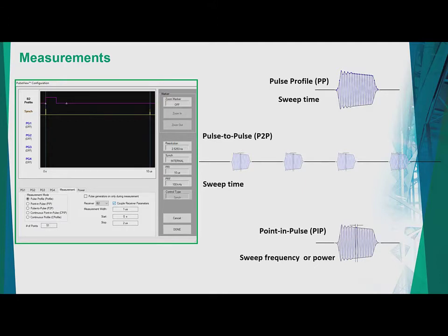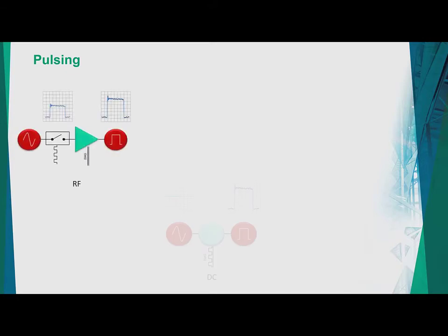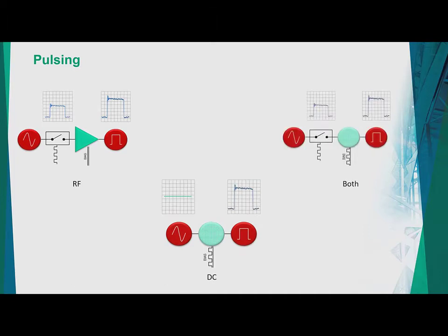We also touched base on why pulse testing is required in various domains. It's a measurement which is more often used by radar applications or people in the radar segment, especially the system integrators, and it's also used for on-wafer applications wherein the DUTs cannot be tested for a longer duration of CW waves, and that's why they need pulsing. The pulsing can be done on two grounds. One is RF pulsing, and the second could be DC/IV pulsing as well.